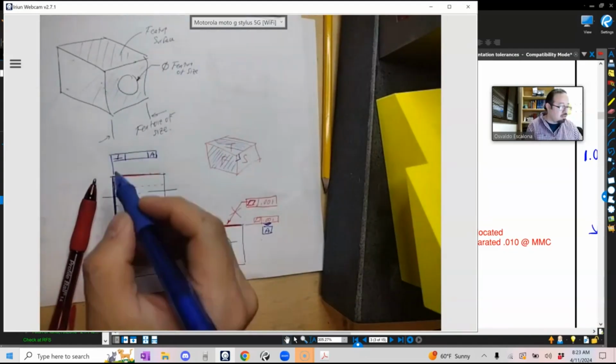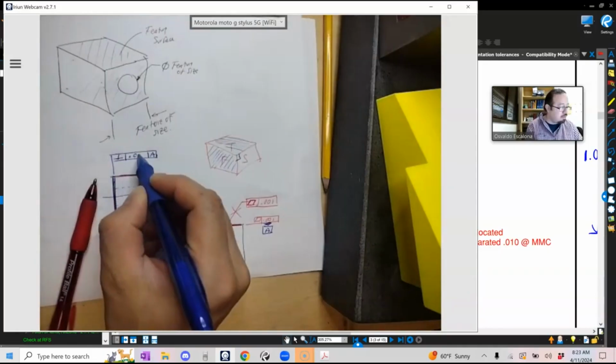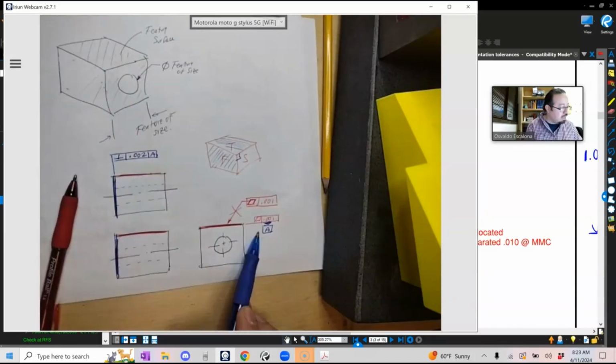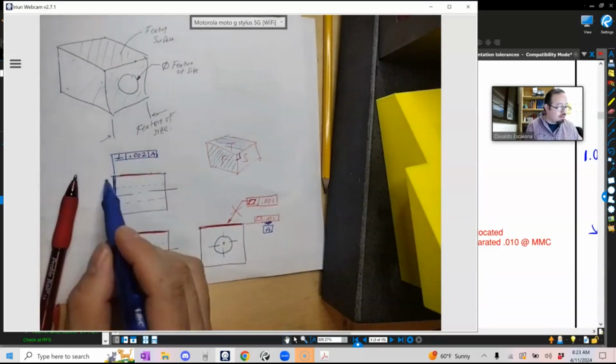And then I gotta tell it, okay, how much tolerance am I gonna give? Let's do 0.002 inch. And for now, you guys will see the placement. I try to keep it clean. You can also make errors, but I don't like errors.